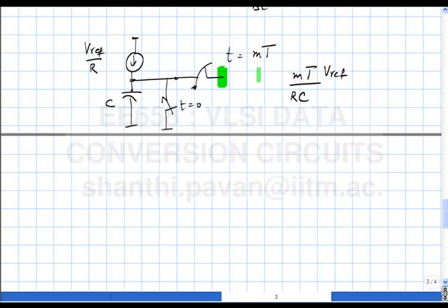Another way of doing it is with RC oscillators. There are many ways of making an oscillator with R and C where the frequency of oscillation is determined by the RC time constant. You can measure that frequency, compare it with the clock frequency, and then figure out if the RC time constant is too small or too large. There are many variants of this technique.